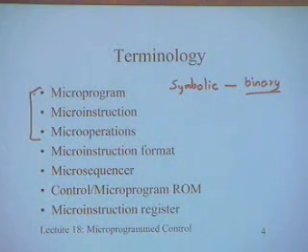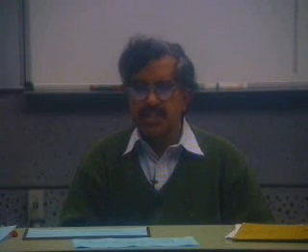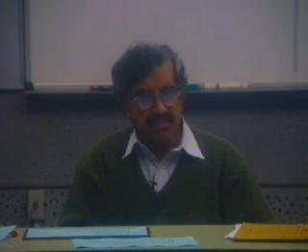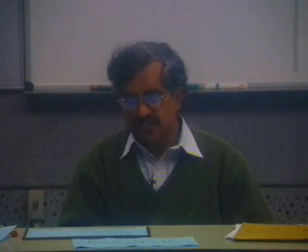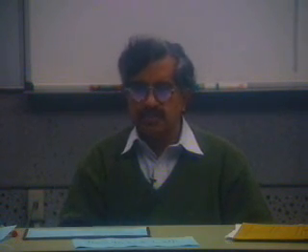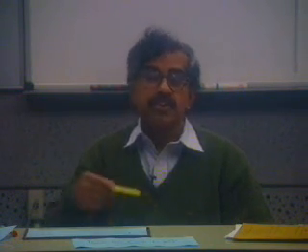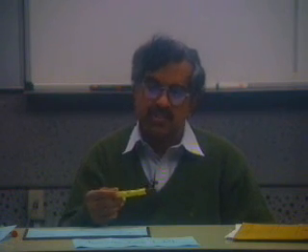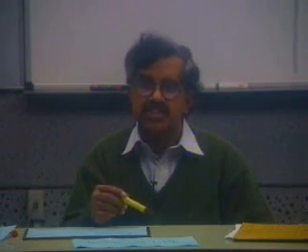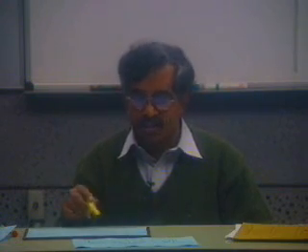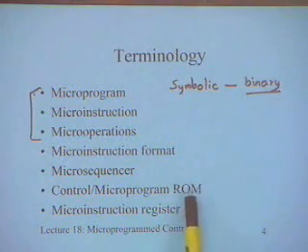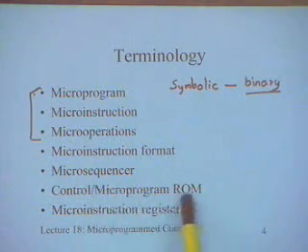Control or microprogram ROM: after all, the sequence of control signals that are required to be generated are stored somewhere, because we are talking of the design of a hardware unit. Once this is designed, it will function exactly the same each time. For example, let's say I am designing a processor, so you are not changing the instruction set each time. The instruction set is fixed. We are only going to give a sequence of instructions, but the instruction set is fixed. So this basically decides how an instruction is decoded and executed in the hardware. All the information, the set of control signals that are required, is of course stored in a binary format in a control ROM.